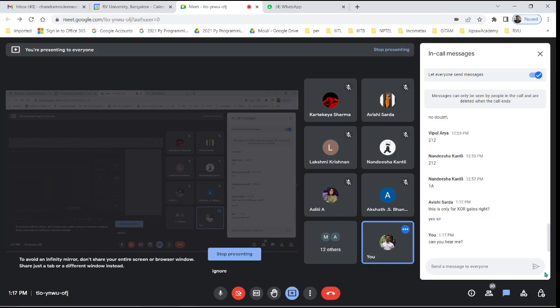What you need to do for the diode characteristic is draw the forward biasing as well as reverse biasing, and then write what the current direction is, what ID and VD are, and the cut-in voltage. Please mention those things, and that's what you are supposed to do for the last question.